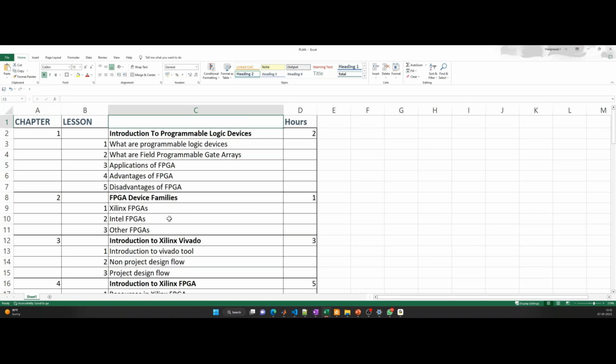Then we will be moving into Vivado. Vivado is the tool set where we will design our entire FPGA based tool flow. This FPGA flow also has synthesis, placement and routing, and bitstream generation, same as the physical design flow. But in physical design, most of the things you do manually. You have to design the transistors, and there will be some libraries, but still most things you take care of manually. Even though the tool automates it, here most of the things you tell via XDC files, the design constraint files. The tool will take care of how to place and route.